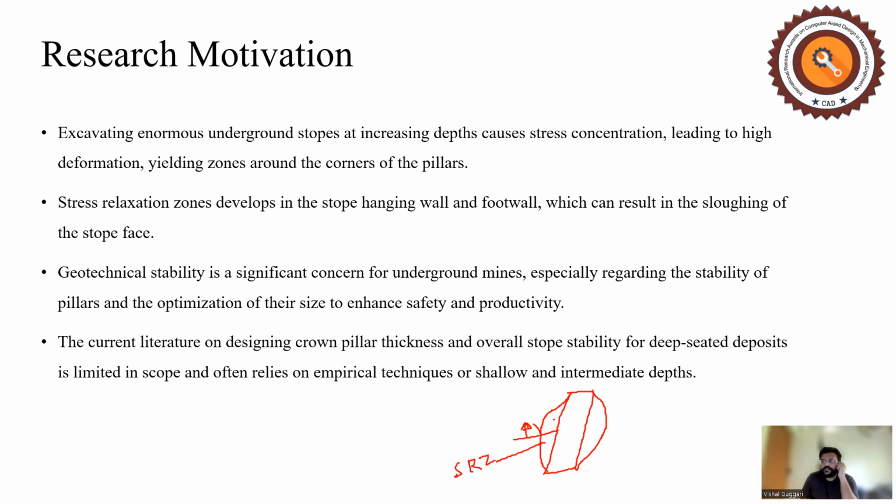These stress relaxation zones develop tensile stresses, and this tensile zone, or stress relaxation zone, may fall into the void space at any time. Hence we need to know the behavior of this relaxation zone, and we need to design a crown pillar in such a way that this relaxation zone gets minimized or stabilized, and the crown pillar should also be stable.